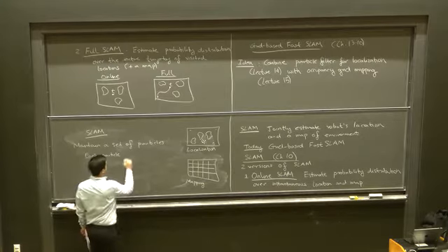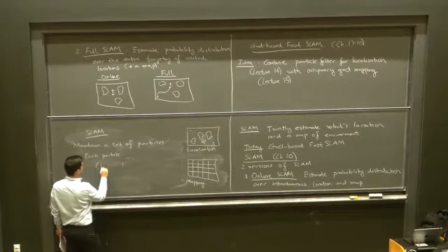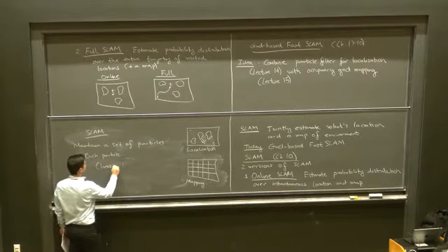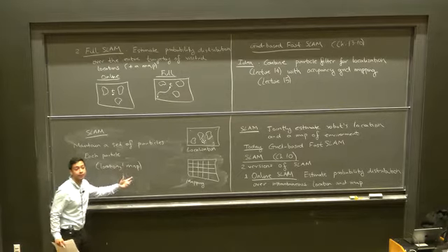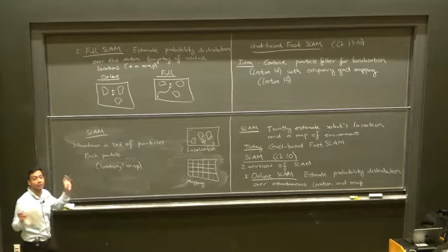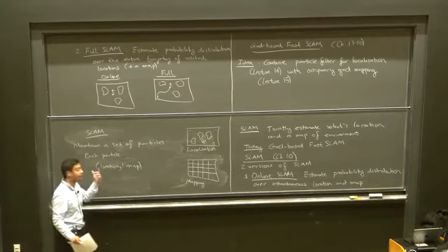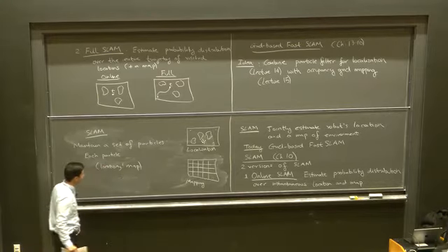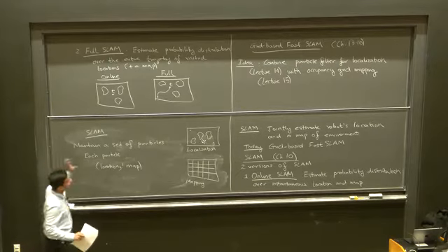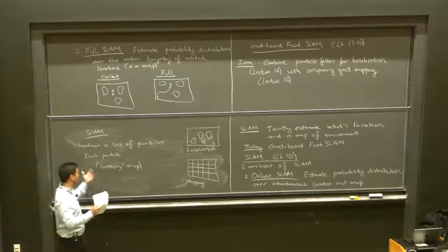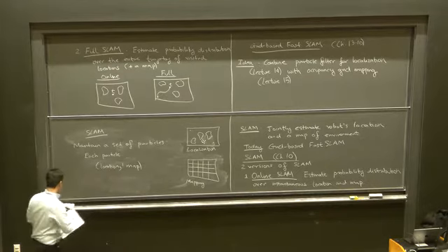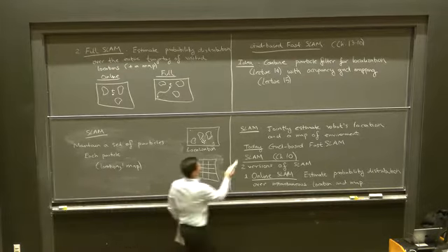One is a candidate location, and a second is a map. So you can think of a particular location and a particular map as corresponding to a particle. That's one particular hypothesis about the robot's location and about the map. And in this particle filtering approach to SLAM, we're going to maintain a whole bunch of these pairs. So I think maybe it's easier to visualize this with a picture.